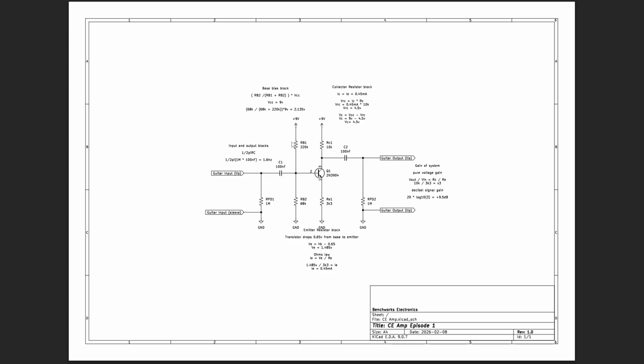It's essentially 0 Hertz. So when you compare that to our guitar input, which is an AC signal or audio signal, which does have a frequency, we can see where this 1.6 Hertz is quite a nice number, because it'll stop the 0 Hertz coming through, but it will let all of our guitar signal above 1.6 Hertz pass.